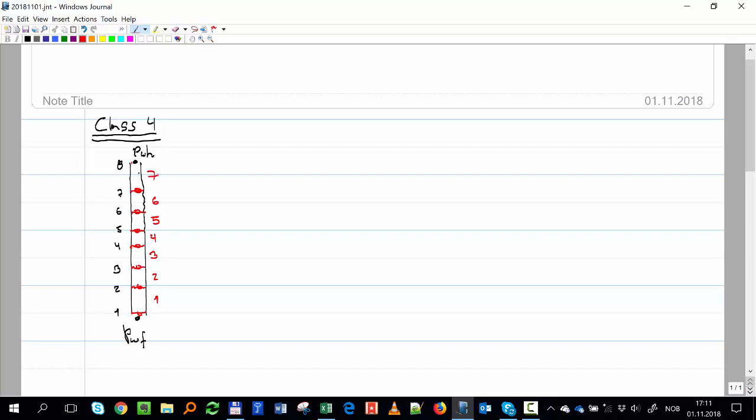And you see that if I have 8 points in the tubing, each one of them has their own TVD, right? If I measure it from here, or MD, then point 8 will have 0, 7 will have a few meters down, and so forth. So in this case, I cannot just apply the equation from top to bottom or bottom to top. I have to apply it to find this point, P2. Here I will have P2, P3, and so forth.